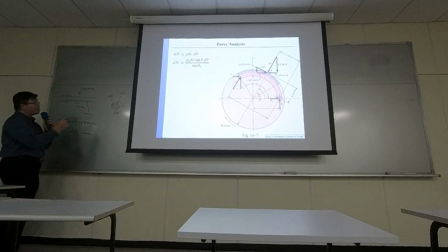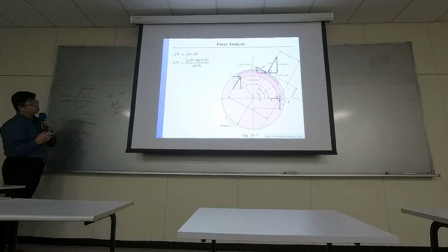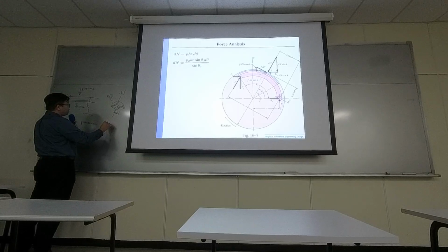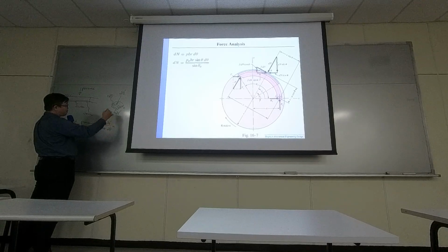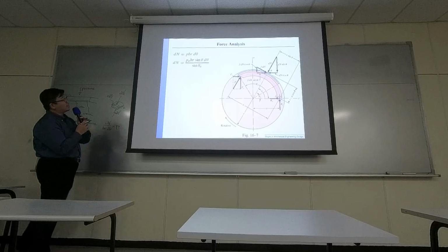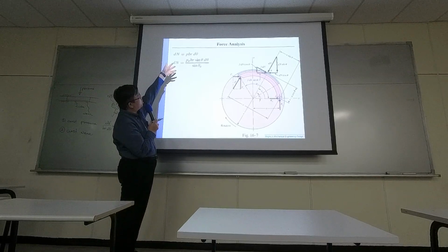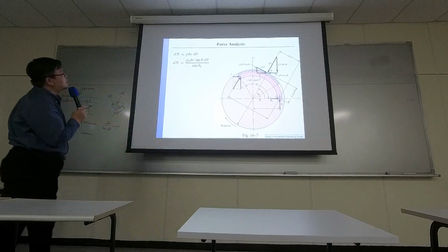Then B would be the thickness right here. So the area, if you have force over area, area is B r dθ. Then you have pressure. Okay, so right here you have dN equals P times B r dθ, where P is pressure.